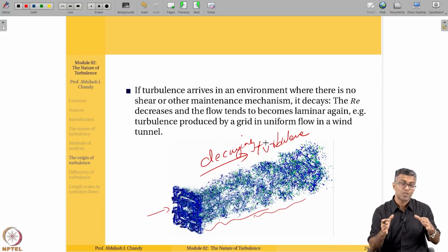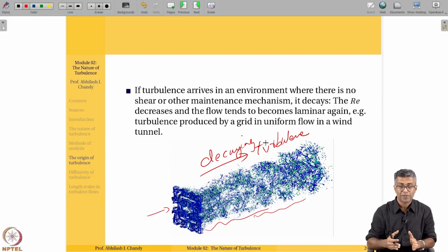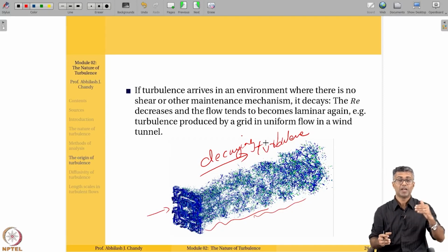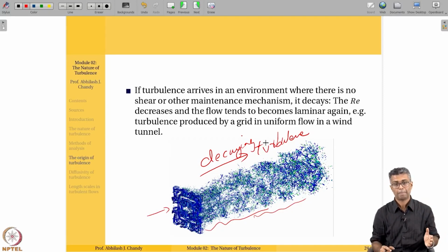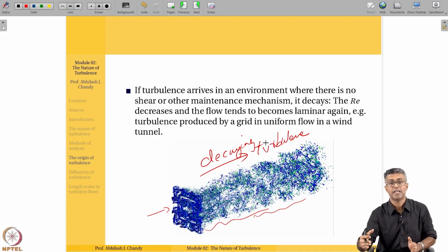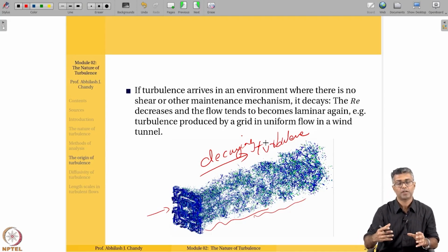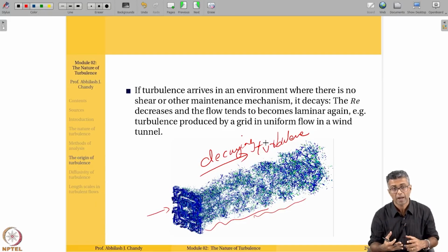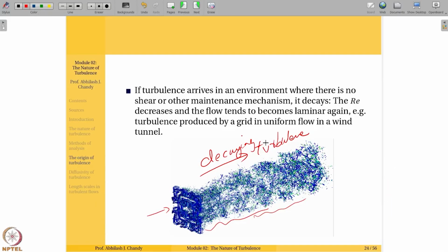This is what Taylor used as his hypothesis to convert the spatial data into temporal data. This was Taylor's hypothesis that I have discussed in module 1. It is this kind of data where the turbulence decays over space, and this could be converted into temporal data and used for several correlations, even for comparing computational models, for correlating with other experiments, and so on.